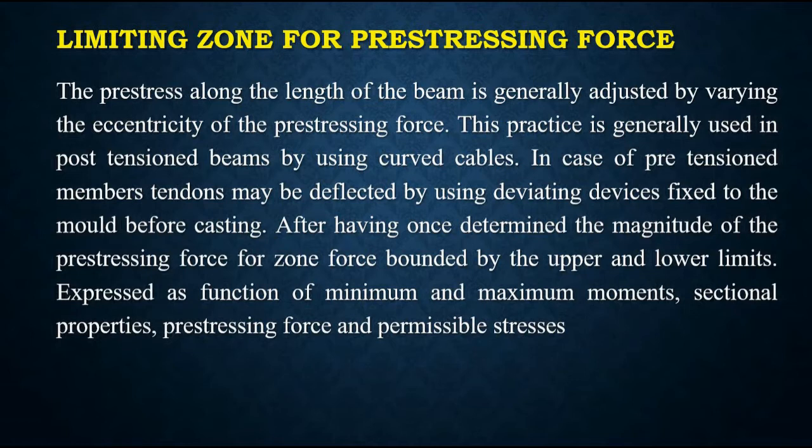After having once determined the magnitude of the prestressing force, the zone for the force is bounded by the upper and lower limits expressed as a function of minimum and maximum moments, sectional properties, prestressing force and permissible stresses.